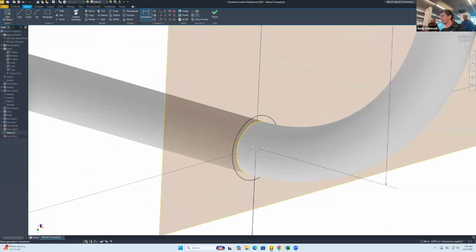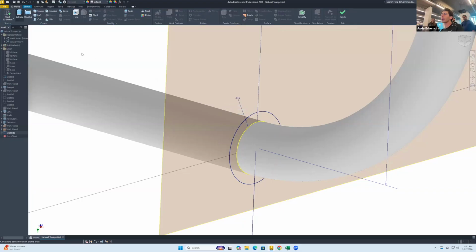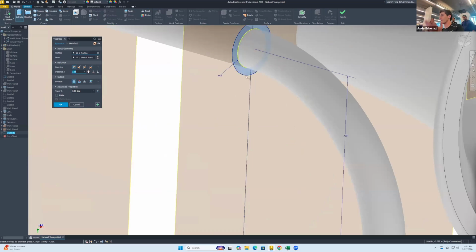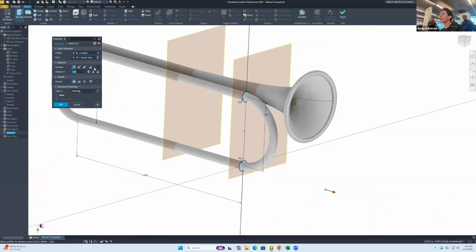And then we can chamfer it and make it look a little bit nicer. The same thing in here. 0.015. And we can extrude. Obviously, it's going in the wrong direction. But we can say, all right, I want to do extrude like that and do it for 0.3.